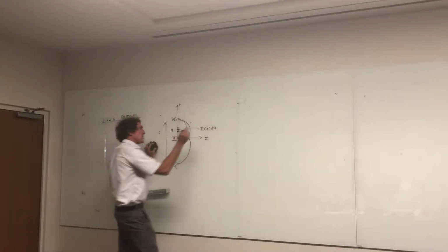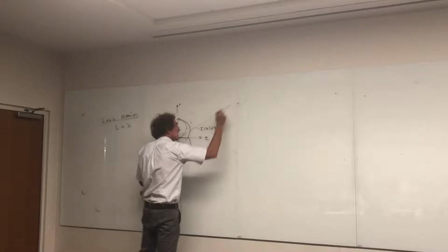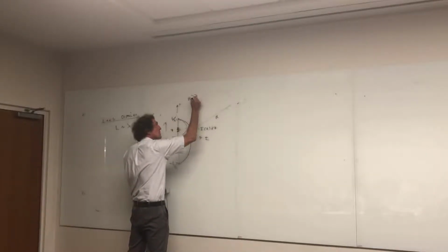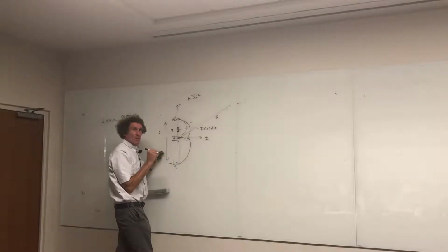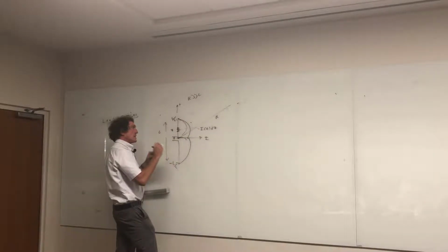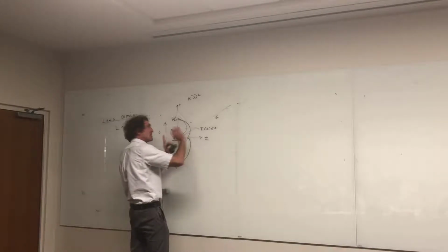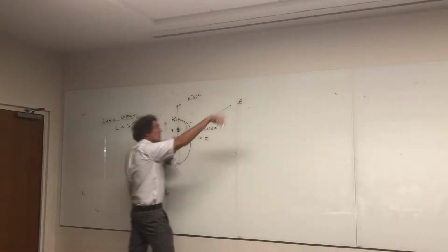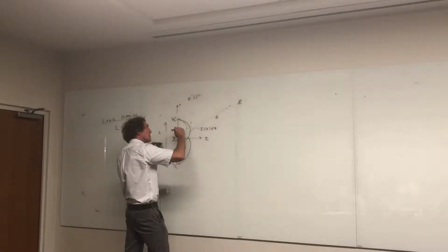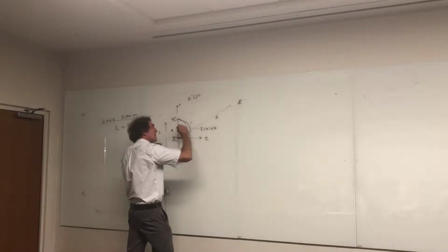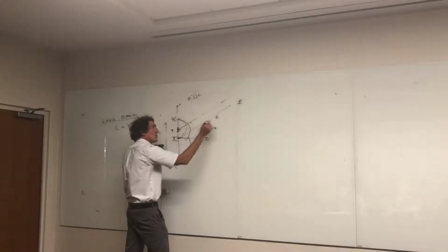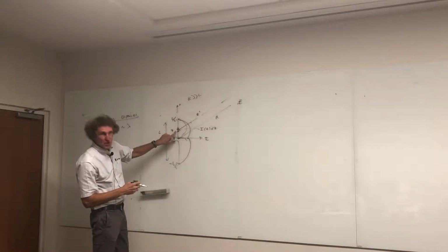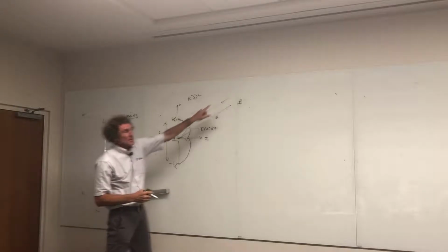Now, the way it's classically done, is you're going to take a radius vector r here, and you're going to say that r is much greater than the length of the antenna. We're going to ensure we're in the far field. Now, this point of observation out here where I'm getting the E field is a long way away. Now I take another ray, and this is about parallel to that one. Follow me? I'll call this R, I'll call this R prime. This is the one from the actual differential chunk of current right here going out to this point.